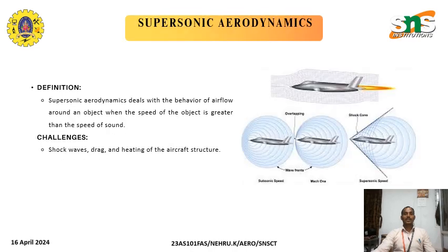Coming to supersonic aerodynamics, which deals with the behavior of airflow around an object when the speed of the object is greater than the speed of sound. Challenges are mainly the shock waves: normal shock, oblique shock, and bow shock, produced before the object, which cause high drag and high heat on the aircraft structure.